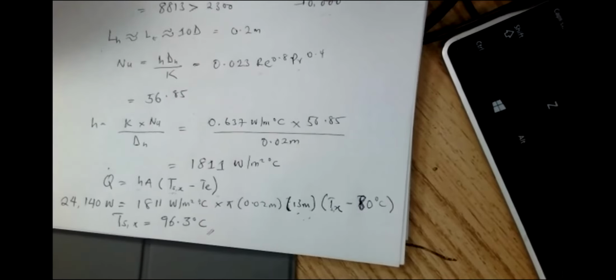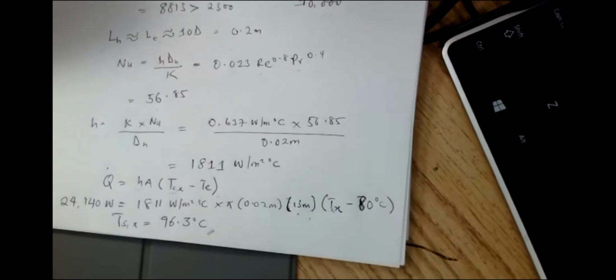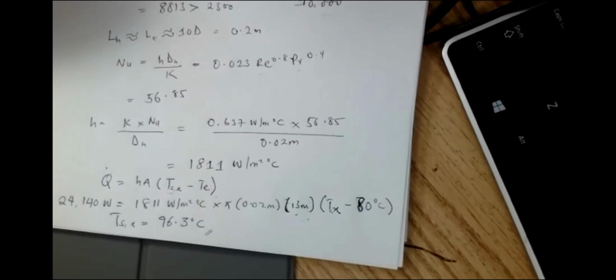So it's question 17 in chapter 4, which says metal plates with a thickness of 1 cm are being heated in an oven for 2 minutes. Air in the oven is maintained at 800 degrees Celsius with a convection heat transfer coefficient of 200. If the initial temperature is 20, determine the temperature of the plates when they are removed from the oven.